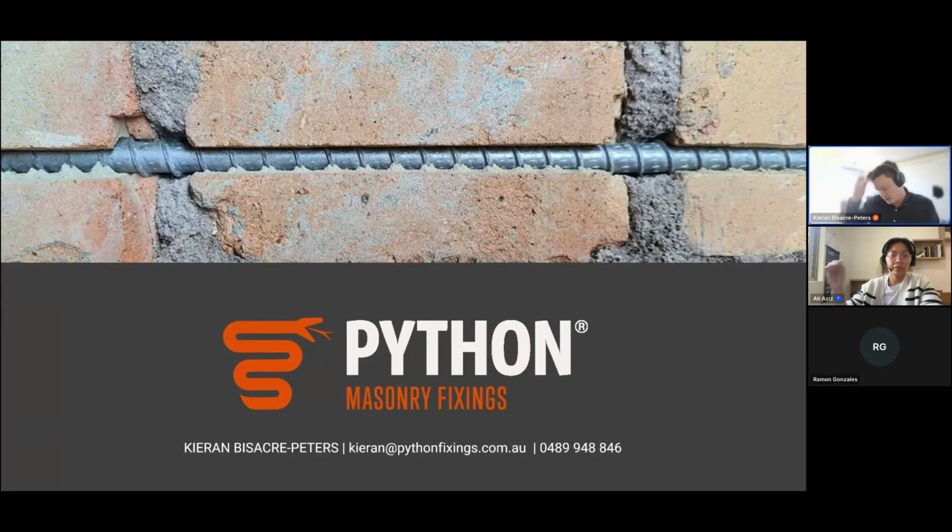Good question. So minimum edge distance, we have a general requirement in our documentation of 30 mils from the edge of a clay brick and 50 mils from the edge of a concrete masonry unit. In instances where you don't know where the edge of your bricks are, or you have to prefabricate steel and you don't necessarily know where the tie is going to align, if it'll be in the center of the brick, there's a few different approaches.